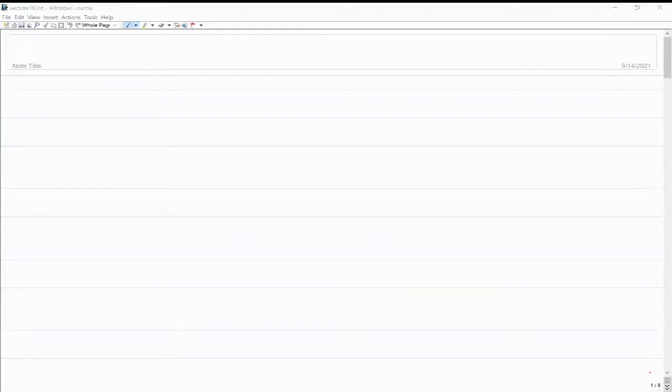Because the moment is going with the rotation, and rotation is theta x or theta y in case of first order shear deformation theory. So the moments would go corresponding to theta x or theta y degrees of freedom, not with del w by del x or del w by del y. Because the actual rotation of the normal is given by theta x, theta y, not by del w by del x or del w by del y.